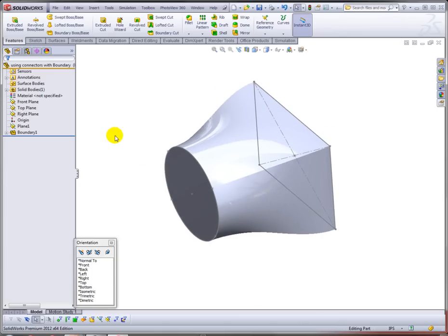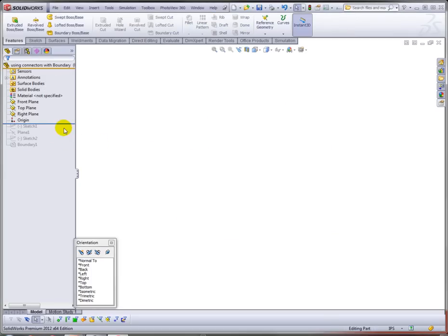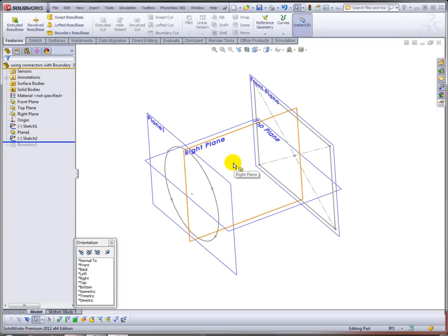Well, insert into your feature, which, as you know, if you want to actually unabsorb the sketches temporarily, you can do that. That's what you're doing here. Then roll just before the feature, and now you have your sketches that are being used currently by your boundary. The reason I'm doing that is that I want to create another profile of this circle that's just inboard of this.